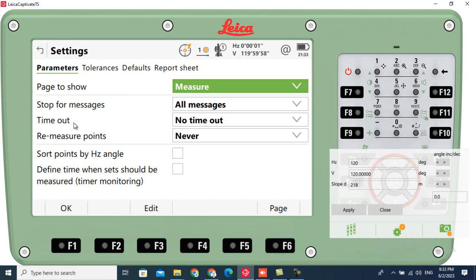He wants to tell you, I can't measure it. Sometimes we make a measurement on a train or on a busy route. If you want to measure a target and a bus or a car goes in between the total station and the target, the total station wants to see the target for a short time. If the car stopped between you and the target, you won't be able to measure this target.